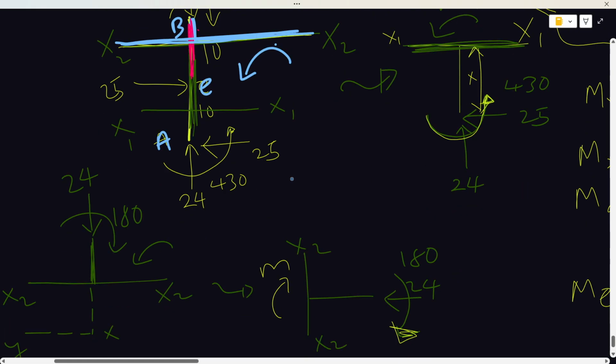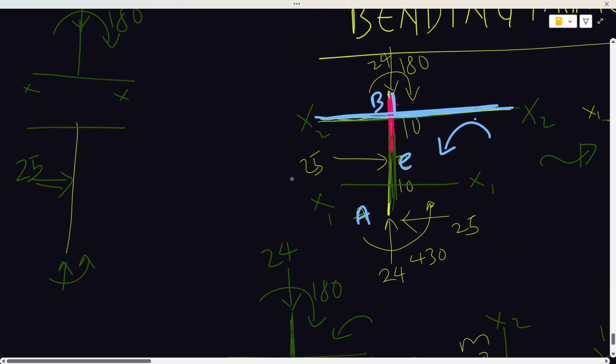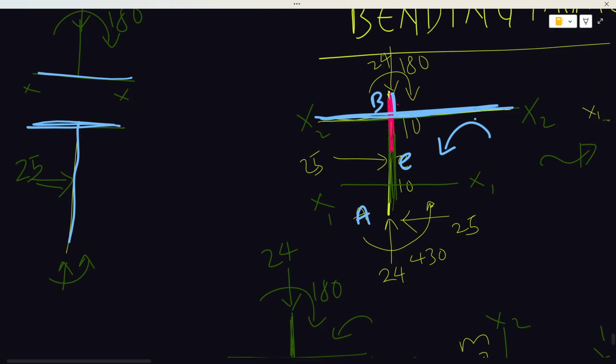There was something I said that you should not try for shear force. When we cut our member, we have two portions, so we can use this portion. Remember that this is the cut part, the demarcator, the cut section. If I want to get moment at E, I can either cut through here, or I can just cut like in the beginning, which is what we did.